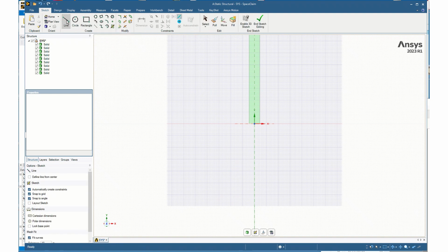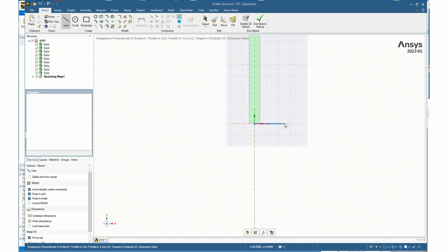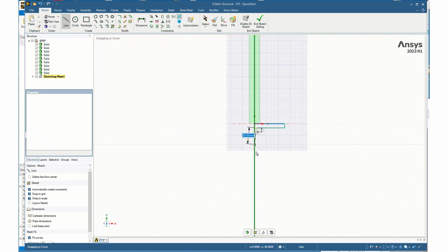I'll click on the line tool, and now I want the center of the I-beam to start right there. So I'll click there, I'll drag this point out, and based on my I-beam dimensions, this is going to be 51 millimeters. So I type in 51, enter. Now I can click and move this down, and I move it down 7.1 millimeters. And there's that line. Click it, move in, and I'm going to move in 48.1, enter, millimeters. And I just keep outlining my geometry like this.